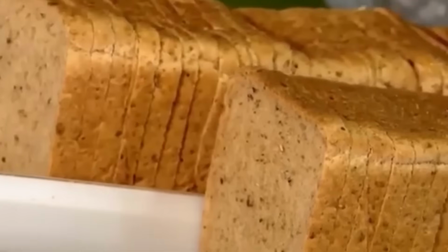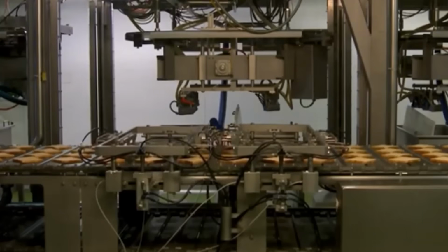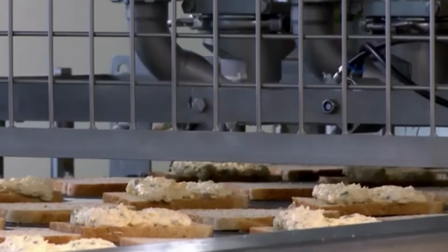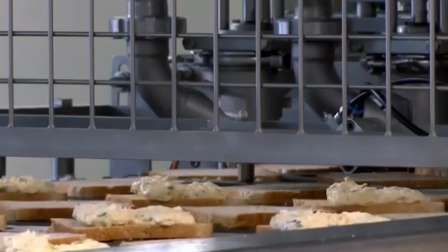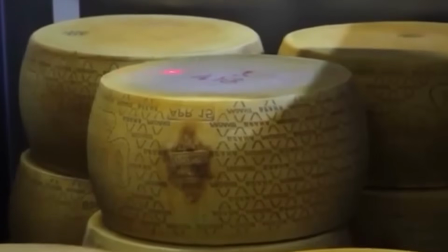Every portion is weighed by inline check weighers before being applied, ensuring that each sandwich receives a uniform protein layer, with rejections happening instantly and automatically if tolerances are exceeded. Next comes the cheese layer, which moves from chilled stacks through a peeling and singulation system that separates individual slices, removes any protective film, and transfers them to a placement module.